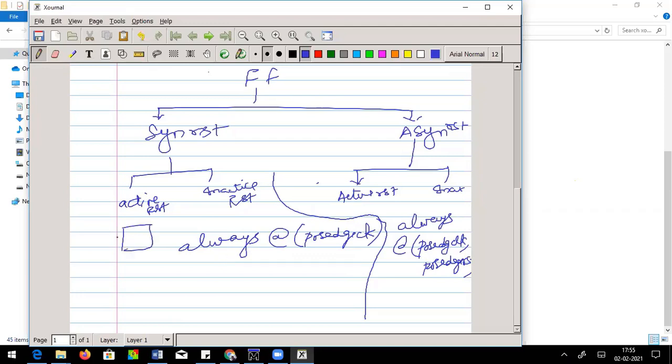Say your system is working. Let's have your D flip flop, D to Q. Now, this is my clock. This is my reset. If you give reset equal to 1, then the output will not go immediately to 0. This will come into effect only during the next clock cycle, the posedge of the next clock cycle. That's what this says. Though you make reset as 1, that is in sync with the clock, whenever the clock edge takes place, then alone it will happen. You can also have this as a negedge also, as I said.